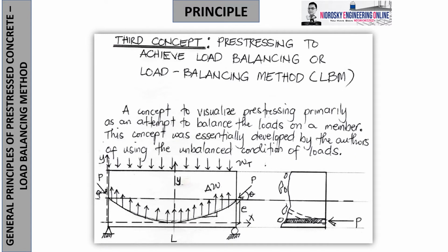Okay, suppose that we have this beam. Actually, si concrete beam can have different sets of what you call these tendons. Most likely, what is a typically used tendon is the parabolic. Notice this is parabolic. Okay, why? Kasi usually ang beam weight naman is uniformly distributed. That's always the case. Also, some loads like live load and dead load, additional, notional, or yung tinatawag nating superimposed, are all distributed. Kaya usually the adaptation of the tendons are arranged like this.